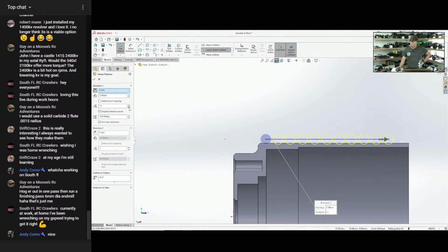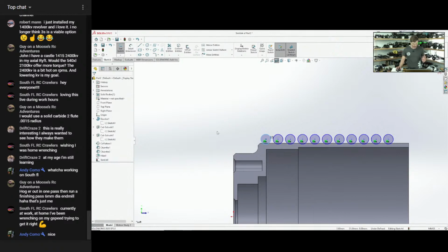We're going to have some other machine features that retain the end of our housing, so we can't go too far. We still need a little bit of bolting room, if you will. It could machine through those features, but it's just not a good idea to have features overlapping from a machinist standpoint. As you can tell, there's a lot of things in design, if you're designing something to be manufactured, that you kind of have to know how things get manufactured. Otherwise, you don't know where your problems may be.